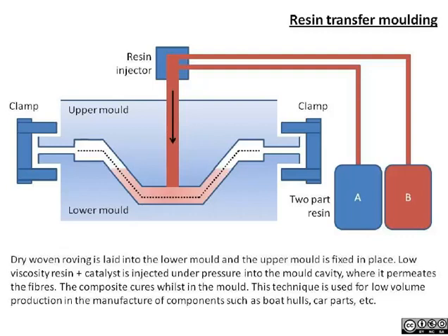Those are pumped into a mold and mixed during the pumping, so it's very important to get these mixed very well, because if it's not mixed well, it won't cure. And then we'll have uncured spots that don't achieve mechanical properties. We can apply heat to the mold to help the cure, make it cure faster or make it cure more evenly, and then take the mold apart.